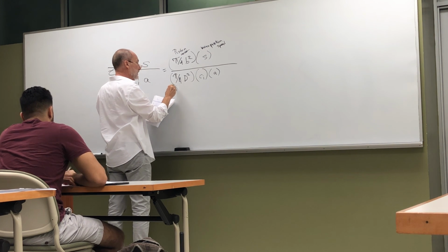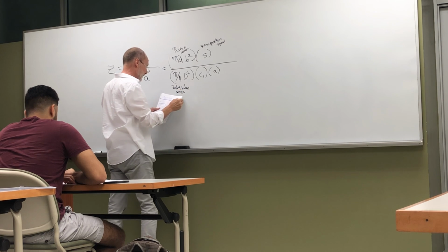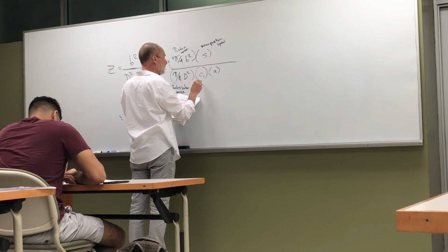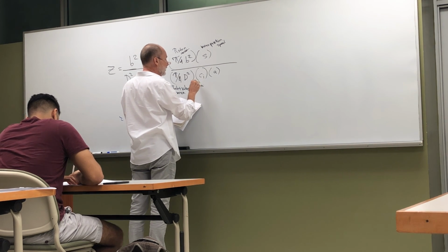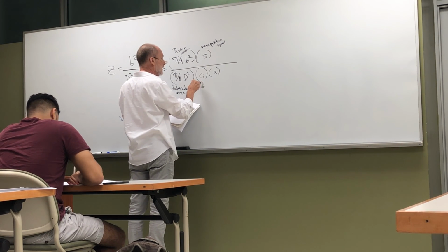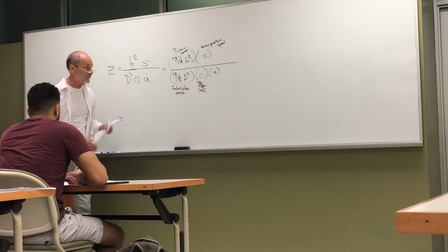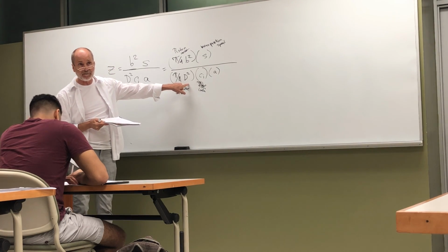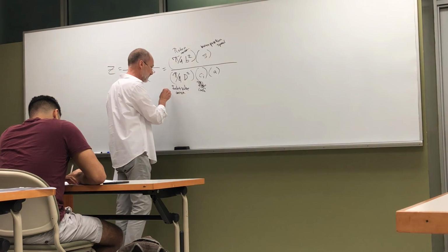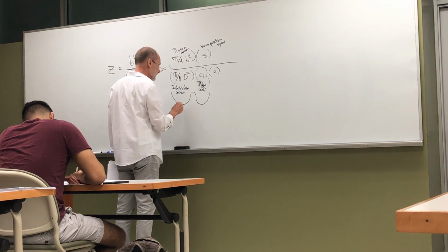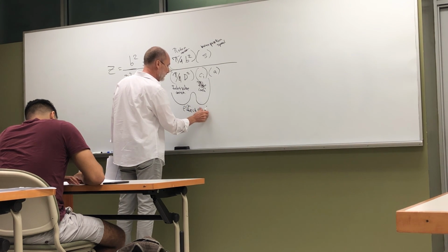And this is inlet valve area, and this is the effective. By the time I've multiplied this times this is the flow coefficient, which is derived by taking the idealized flow. You calculate what would be the isentropic flow through this area and divide it into the measured flow, getting the flow coefficient. So this all together becomes the effective inlet valve area.